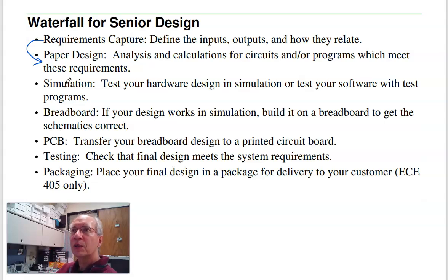If you're stuck with something being arbitrary, like you don't know how to calculate this resistor, that's usually a sign of weak requirements. If I just say drive an LED, that's too vague. If I say drive an LED at 20 milliamps, now I know how to calculate the resistance.